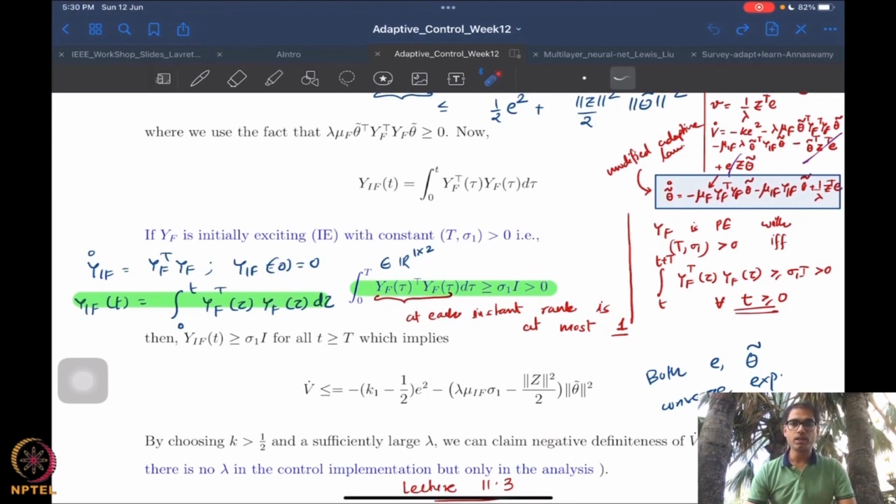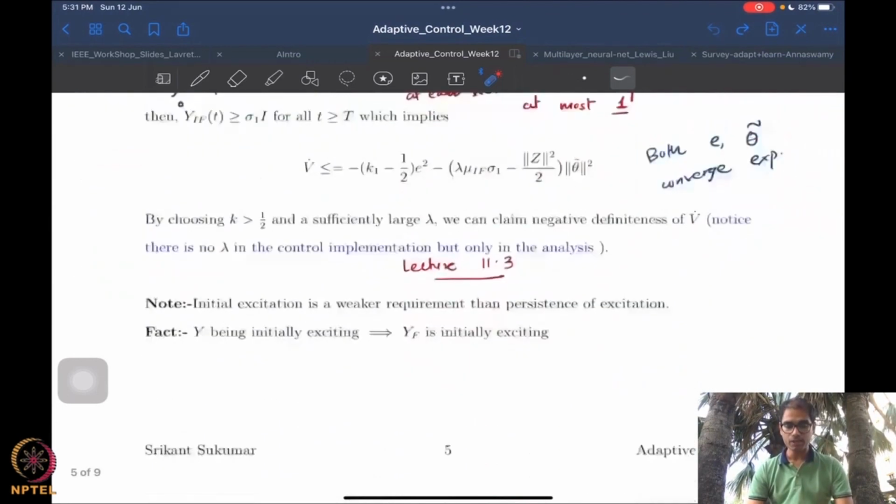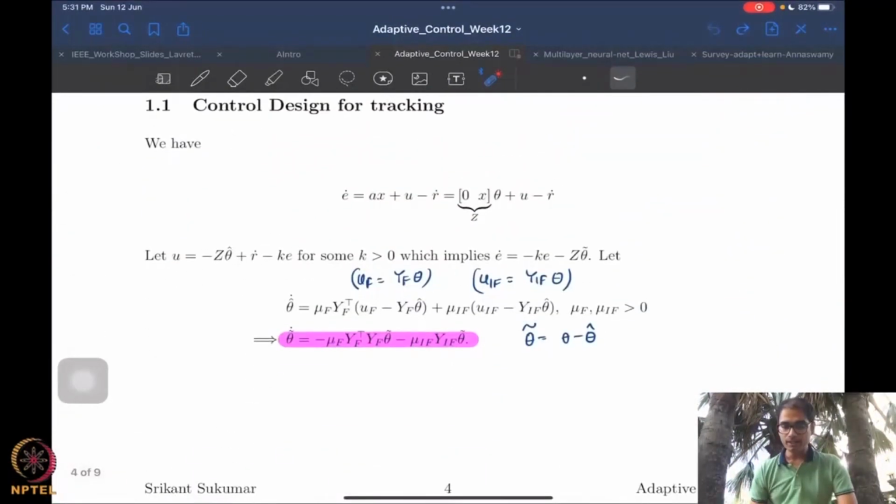We also saw that it's possible to alleviate some of the limitations by slightly modifying the initial excitation design to add a certainty equivalence adaptive control term, right? So keeping that in mind, we do hope that this sort of design method helps us to give some improvements, not just in theory. Of course, we've seen in theory that there are significant improvements, especially in the sense that you have these negative terms in your adaptive update law, which was of course not there earlier, right?